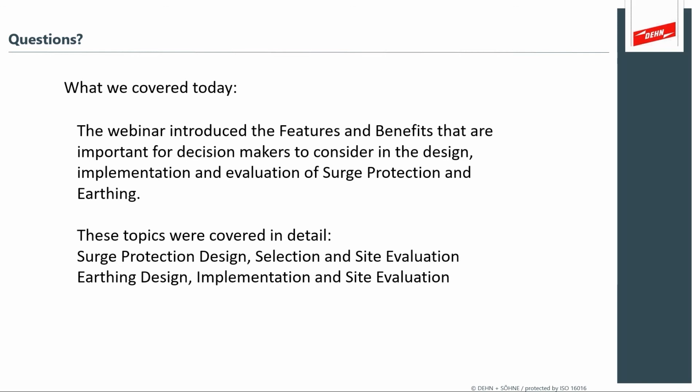Yeah, so in other words, if I can just say back, what you're saying is that the voltage protection level that a surge protection device provides for an installation is not just the rating across the SPD, but it includes the conductor that's run from the phase to the SPD and from the SPD to ground. That's the whole voltage protection level between line and ground that the equipment's going to see. So in other words, the sum of the voltage drop over the top wire from phase to SPD, the voltage protection level of the SPD, as well as the voltage drop from the wire from the SPD to ground, that sum will basically be the final voltage that your equipment will see.